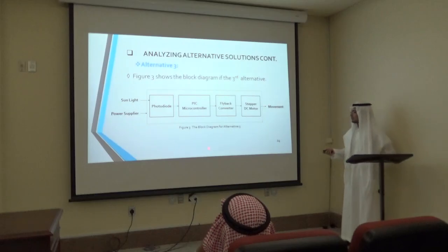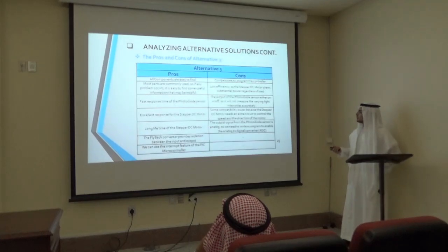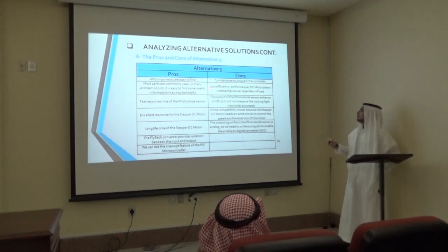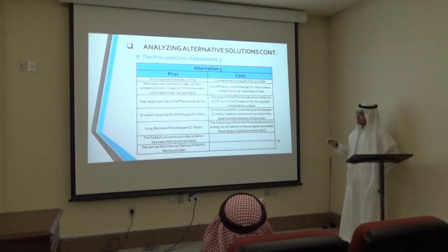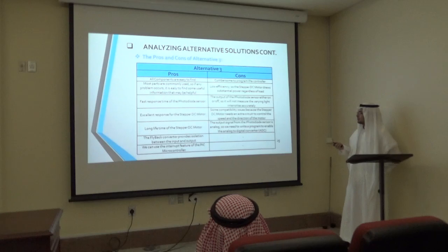It's like the previous, but we replaced the LDR sensor with the photodiode, the Arduino with the PIC microcontroller, and the boost converter with the flyback converter, and we use the stepper motor. The main problem in this design, the stepper motor has low efficiency. So the stepper motor has a high power consumption, which does not help us to achieve one of the main goals of the project.